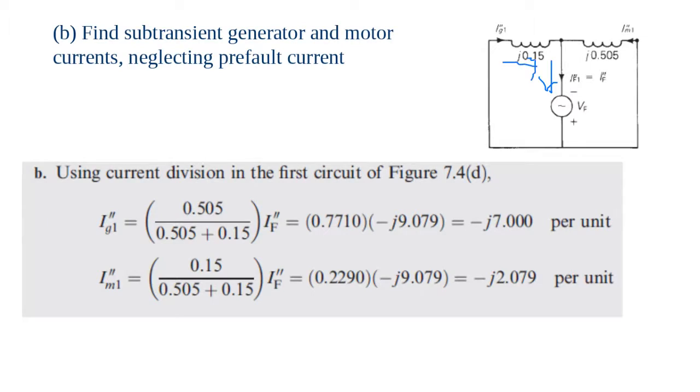I motor is going here. They all come to the fault. Okay, very good. But before the fault, where does the current flow? Can you give me that now? Before the fault, we don't have this short. It is not present. So where is the pre-fault current? Okay, the load current. Pre-fault current means the load current before any fault.